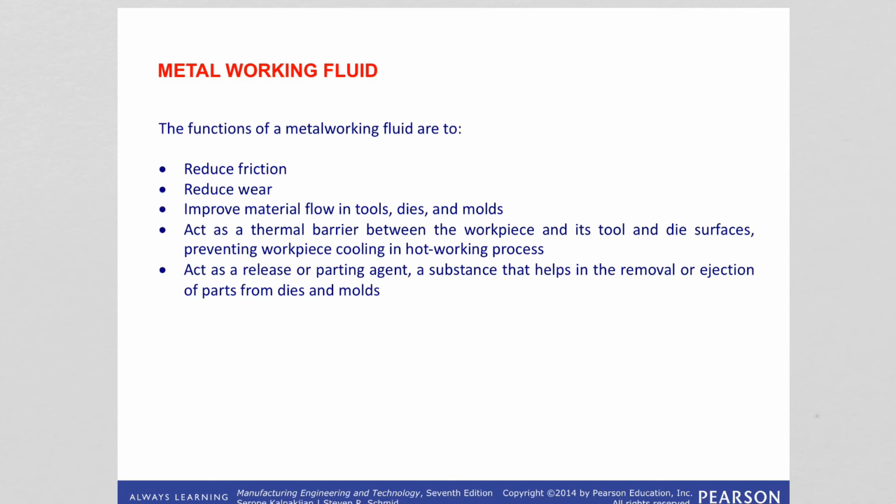It will improve material flow in tools, dies, and molds. It will act as a thermal barrier between the workpiece and its tool and die surfaces, thus preventing workpiece cooling or thermal cycling in hot working operations. It can act as a release or parting agent that will help us in the removal or ejection of the parts from dies and molds.